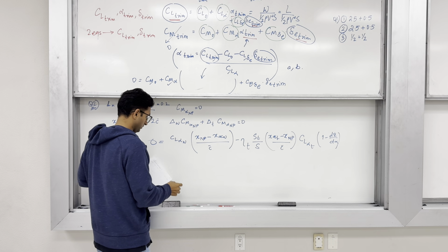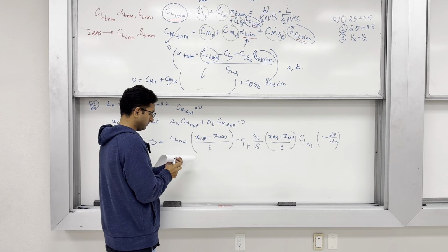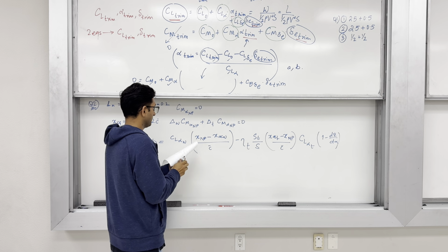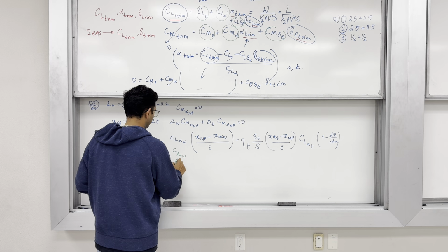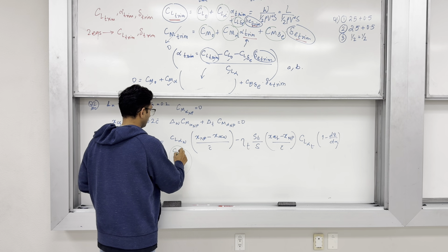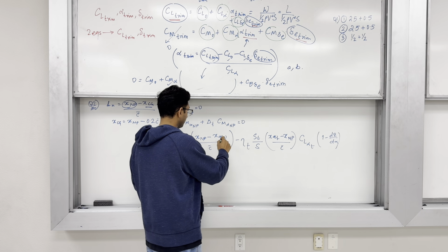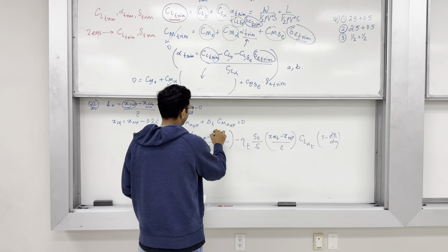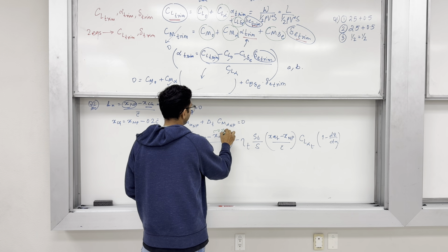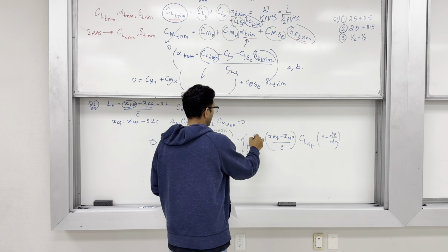Now, CL alpha, I go and look piece by piece: can I find capital CL alpha? Yes, I can. Why? Because I have been given small c l alpha. So, this is the 2D, and I have the aspect ratio of the wing. So, I can get CL alpha done. X AC of the wing, since nothing is mentioned about the aerodynamic center, feel free to make the approximation that this is 0.25 C bar. Eta tail is given as 1.0, S tail and S.